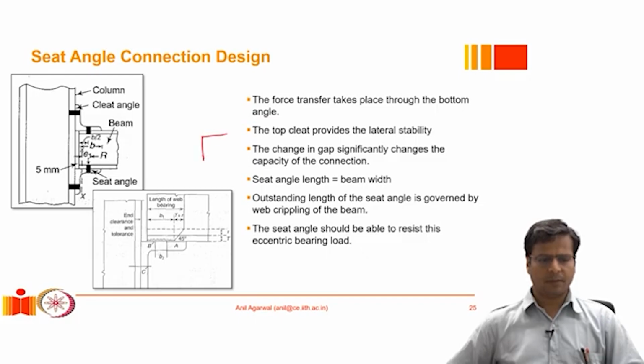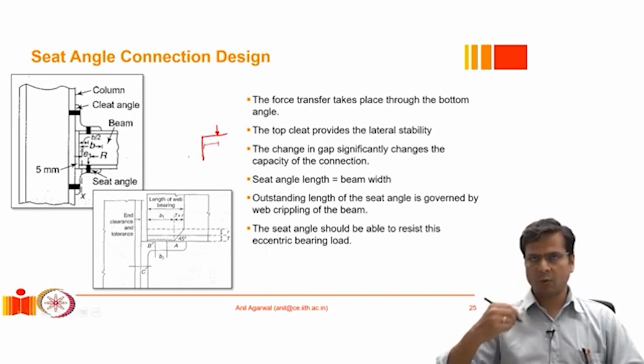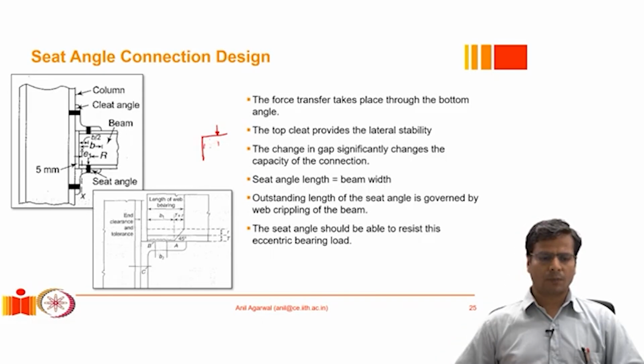if this is that angle, and depending on where this load is acting, if the load is acting close to this edge, like shown here, then the moment demand will be less. Therefore, we don't require a very strong angle here. However, if we increase that distance for the same amount of shear force that we are applying, the lever arm would increase, and therefore the moment demand would increase, and that may require a very high strength angle to be utilized.